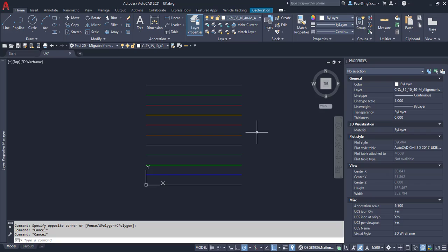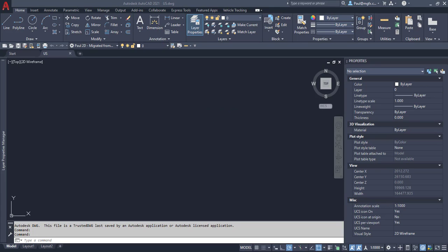Now you can imagine this can be done for standards between countries, or BIM standards, or even between companies. So if you've got a consultant that regularly works for you and they've got their own layer standard, and you would like to from time to time transfer these layers onto the correct layers, even if it's not complete, you would get 70-80% of the work done, and that is what I would recommend. So we're going to have a look at that when we bring this file into the US file next.